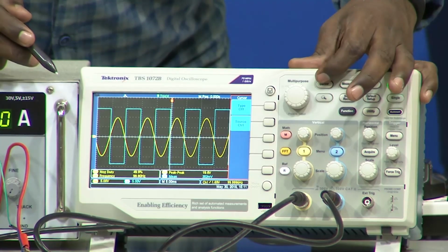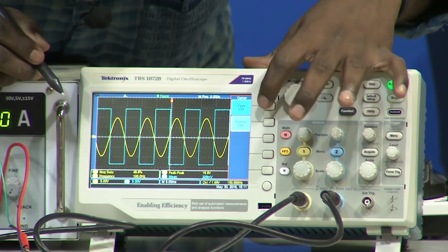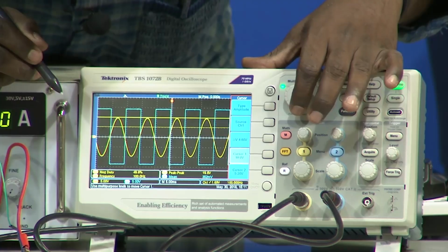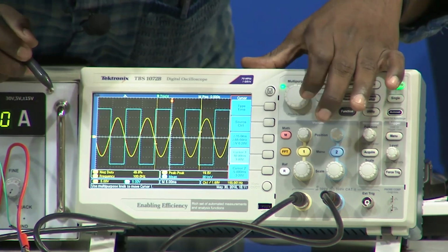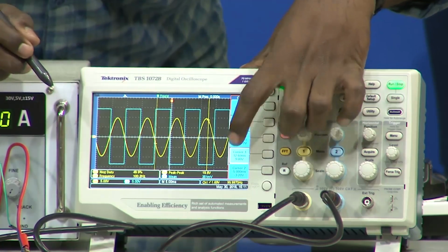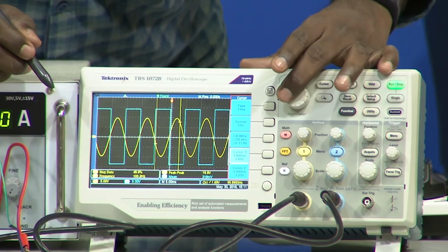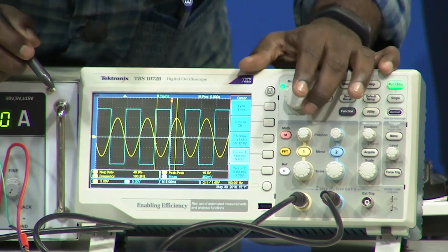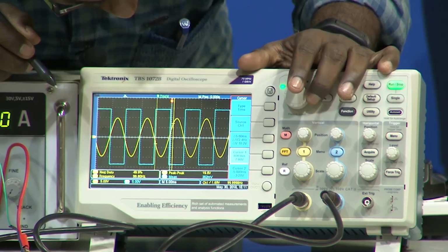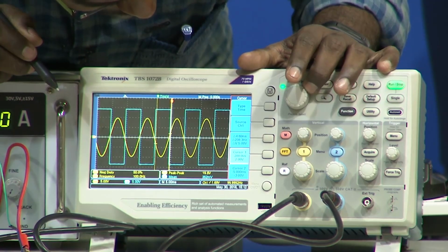So, I will create a cursor here, channel 1 cursor, and I will take time. I select cursor 1, and when you see the cursor 1 reading, I will take any one of the peak values and move slowly towards 1.35. Right now it is at 7 volts, I will decrease it, now it is at 2 volts.